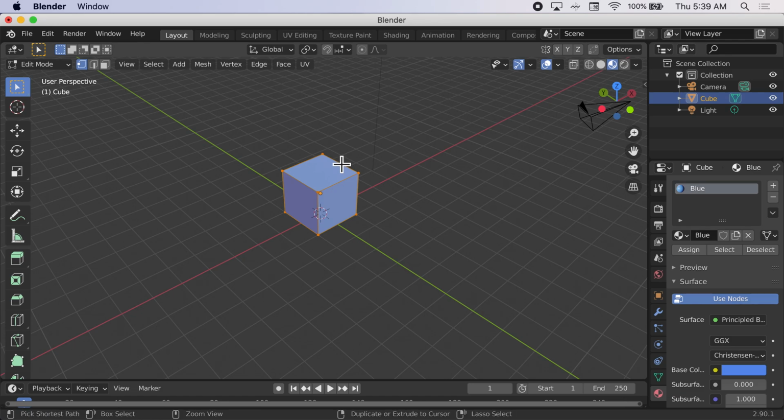So I'm going to hover over this edge and press Control R, which opens up the ring cut tool. Now I want to tell it how many ring cuts I want to make. I'm going to press 2 because I want to make 2 ring cuts. Then I'm going to hit the return key twice. If I press it once, then I can drag around the ring cuts if I want to reposition them. So let me do it again. There you go, Command Z.